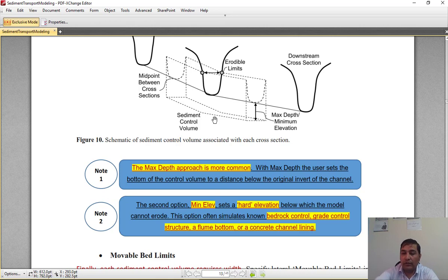If you have an erosive river, you can select higher values for max depth. Otherwise, if you have a river with a smaller rate of erosion, you can use a smaller value for max depth. Overall, a value of 10 meters is a good choice for max depth.